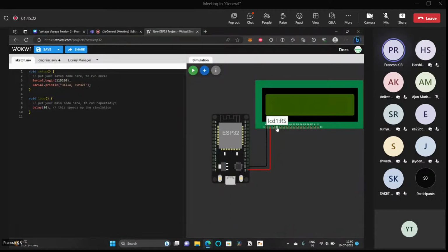These are two registers. Since we have two different actions for the registers inside an LCD, we can't just connect this to 0 or 1, because 0 corresponds to one register and 1 corresponds to another register. So we'll give it to a data pin. So the microcontroller will take care. Are you guys getting?